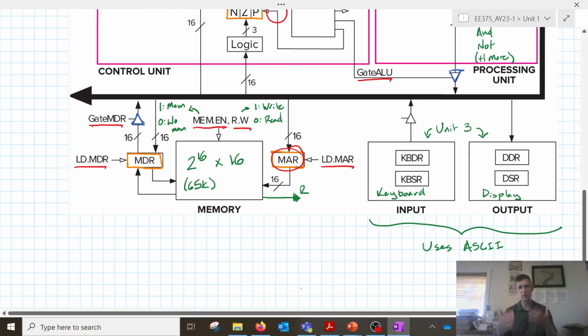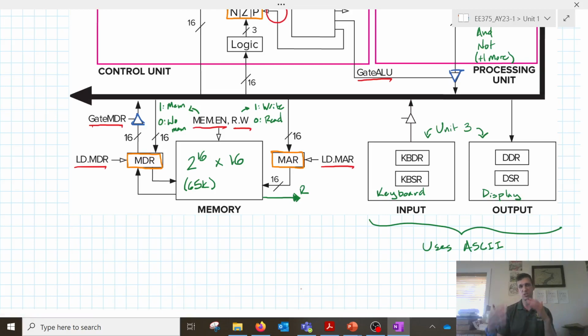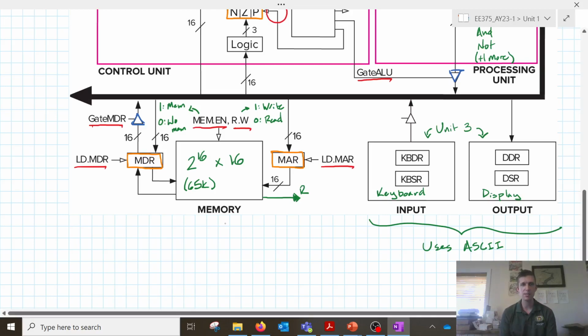Okay, so effectively 3 clock cycles anytime I'm trying to read or write to memory in order to set up these registers correctly. Now, I mentioned that accessing memory takes at least 1 clock cycle. We'll learn later that accessing memory may take dozens or hundreds of clock cycles.